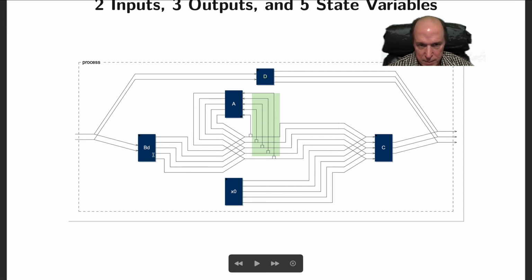All right, so here's our B matrix. It comes in. So this is your state. These delay elements contain the state variables, and the A matrix feeds back around, and then you sum. So this is x of n plus 1 summing with B times U, the input, and that forms the next state. Then the C matrix takes a linear combination of the states and puts it out. On the first sample, time 0, it's C times x0 that goes out. That's your time 0 output. You also add D times U to that. So time 0 is very different from everything else.